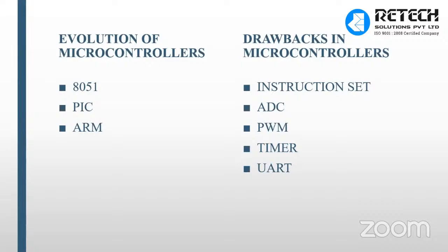I will give another example, an IR sensor. The IR sensor is used for object detection. Whenever an object is detected, it gives the value 1. Whenever an object is not detected, it gives the output zero. We define the output in zeros and ones. These devices are digital devices. Devices we cannot define with zeros and ones, like temperature, gas, and water level sensors, are all analog devices.